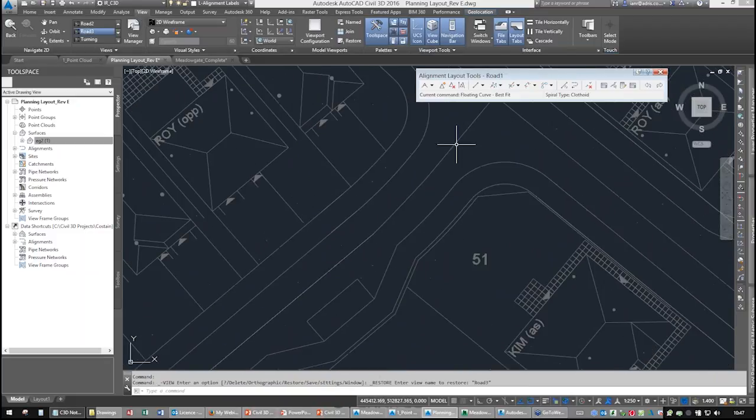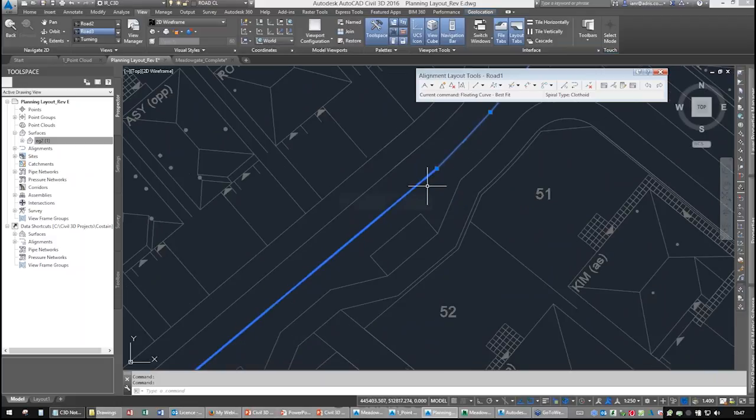I just wanted to show you road 3 here. So the designer here, you can see it looks a bit odd, and I suspect that there are some problems with the geometry there, and I wouldn't be able to design a corridor on there very neatly. We'll get a thing called bow tying, where the cross sections that you put across will cross over each other, so that would be no good.